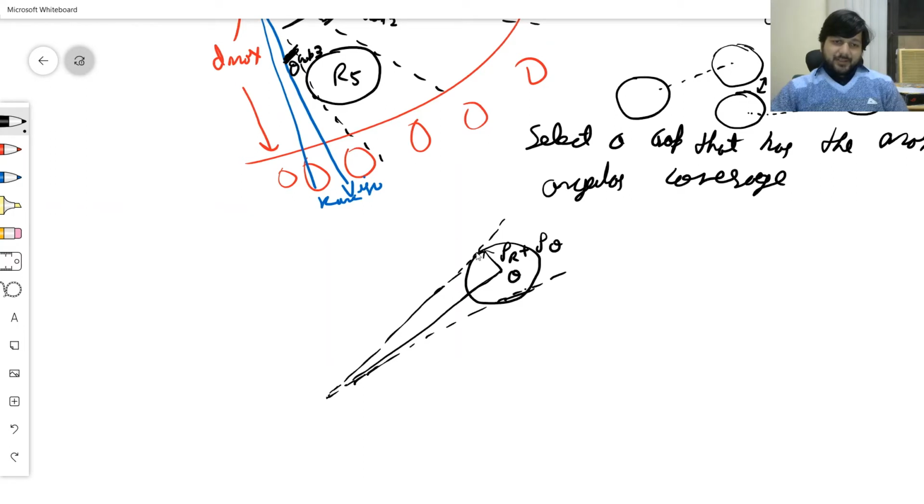So that's the obstacle O. So let's say this is the angle gamma O. So that's 90 degrees. So I have sine gamma O is equal to rho r plus rho O divided by the distance between Q, that's where my robot is, to O.